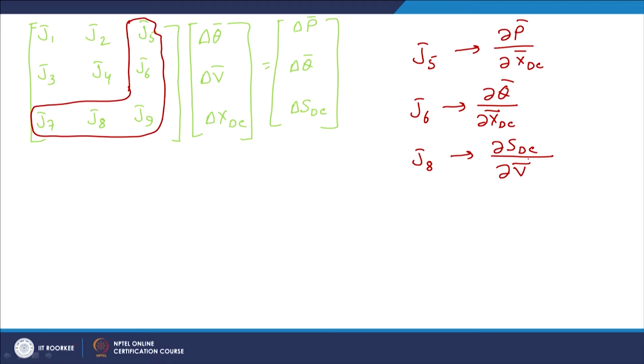So basically what is happening? In the case of the simultaneous approach, we are solving the AC and DC unknowns together. Earlier we had only 4 Jacobian submatrices, but now we will have 5 more extra Jacobian submatrices. As a result, the size of the Jacobian matrix will increase.